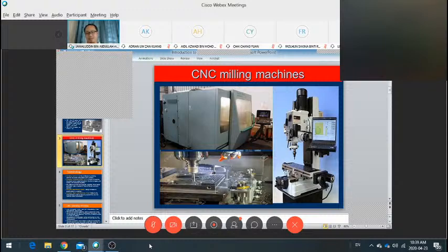And at the end of this table, for modern machines, some of them have an encoder or sensor. What do these two things do? The encoder or sensor will determine the position of the table, and then feed the position back to the system so that you can control the position very accurately. In fact, a CNC machine is very accurate. It can even go down to 1 micron resolution, or 1 micron accuracy in terms of the positioning system.